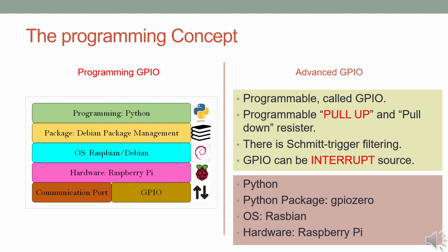This single line tells gpiozero, monitor the button on the specified pin, automatically call my function whenever the button is pressed. This greatly simplifies development and allows you to focus on what your program should do, not how it connects to hardware internally. In summary, the Raspberry Pi supports both high-level communication ports, like USB and Wi-Fi, and low-level GPIO ports for direct device control.